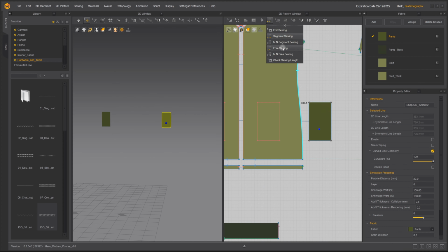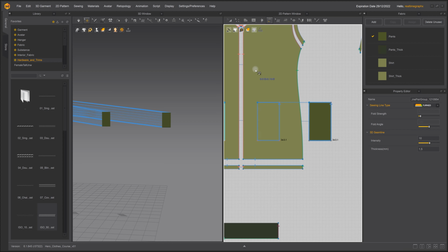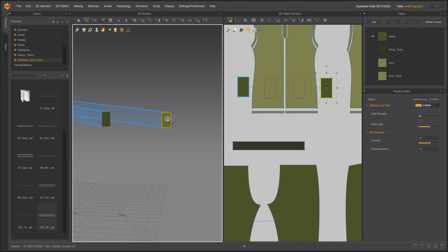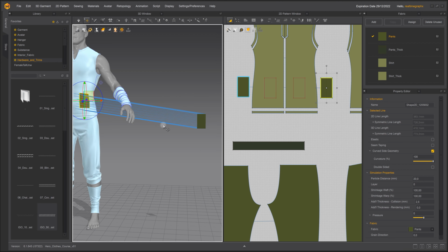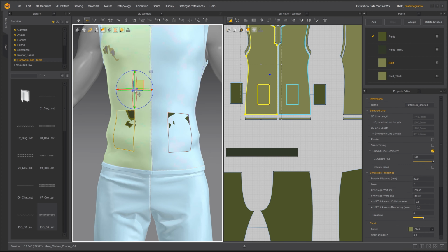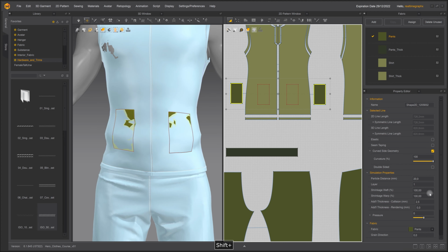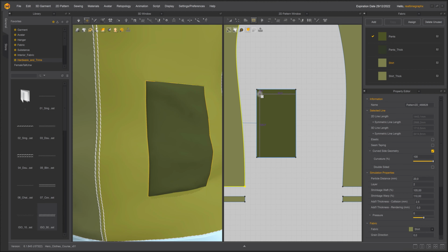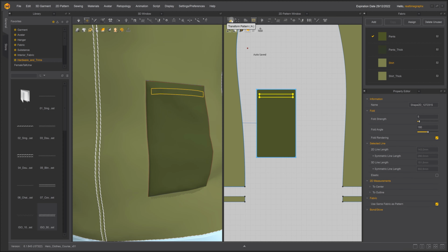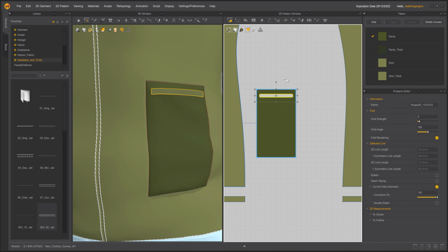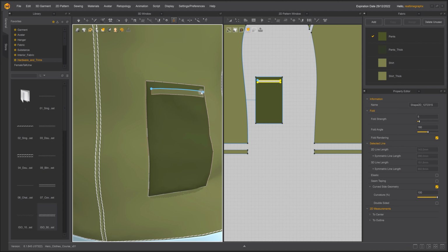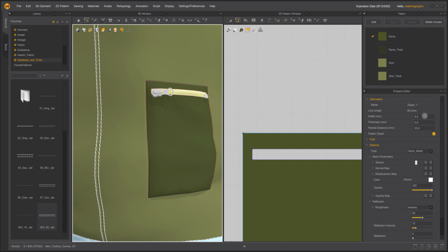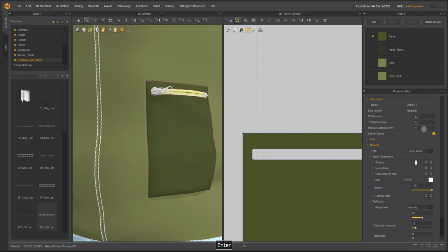First, stitch the pockets to the internal shape, and then right-click on the cloth in the 3D window and select Superimpose Over. Our vest is on layer 2, so we need to set the pockets to layer 3 and then simulate. So these are not real pockets yet, since they have no opening. Let's create an internal shape again, convert it to a hole and close it by using the zipper tool in the 3D window. It's a bit too wide, so let's adjust the width to 3 mm.